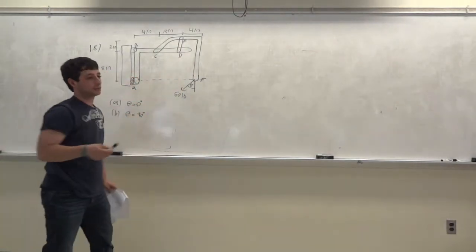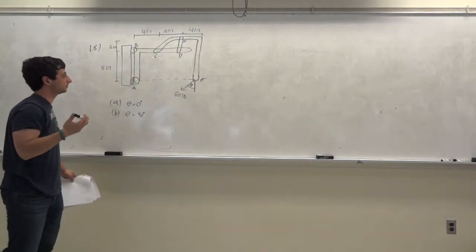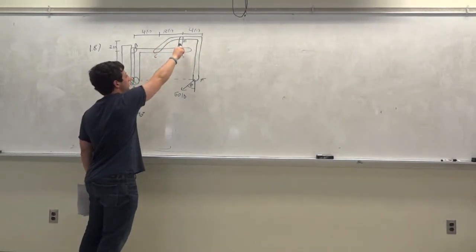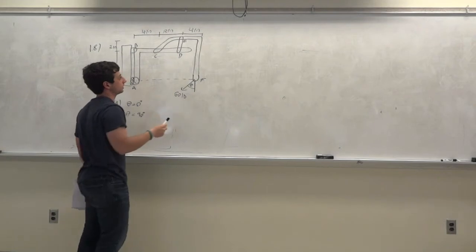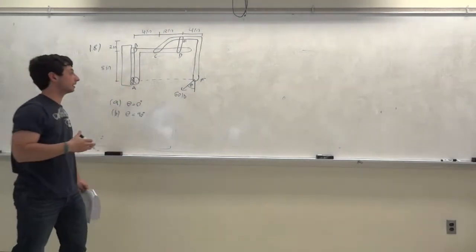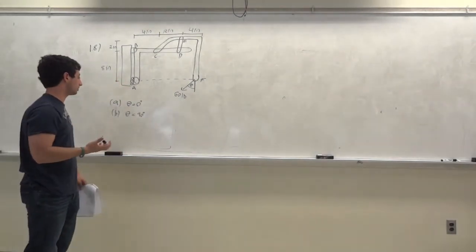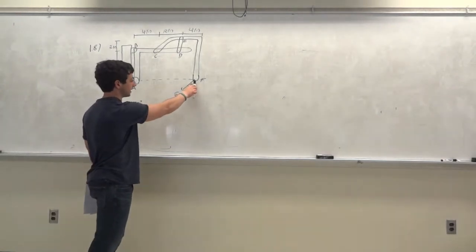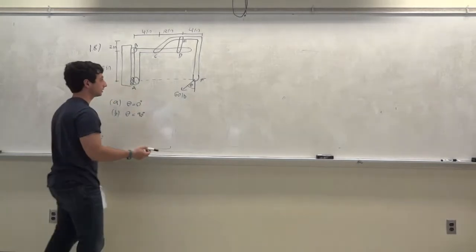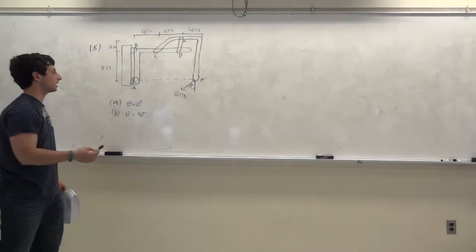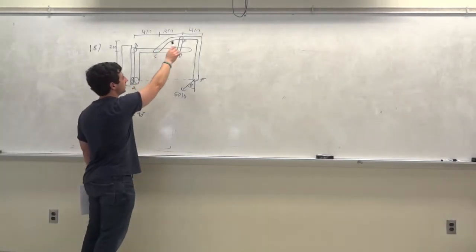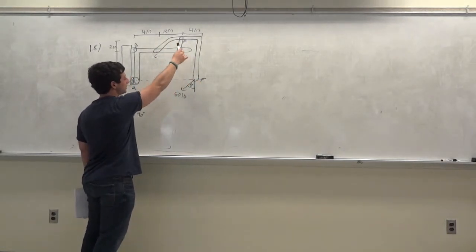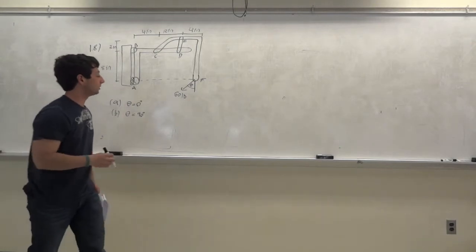So we're going to have to draw a free body diagram of possibly this link, and then we're going to have to know whether this link is in compression or tension, and then we could get the stress in that link. So what happens when theta is 0? You just collapse this onto the y-axis, right? It's on the negative y-axis. So we want to draw a free body diagram of this link, CEF, and also what DE is going to look like.